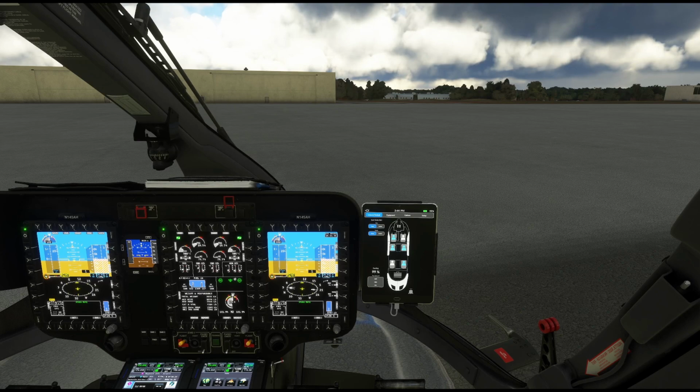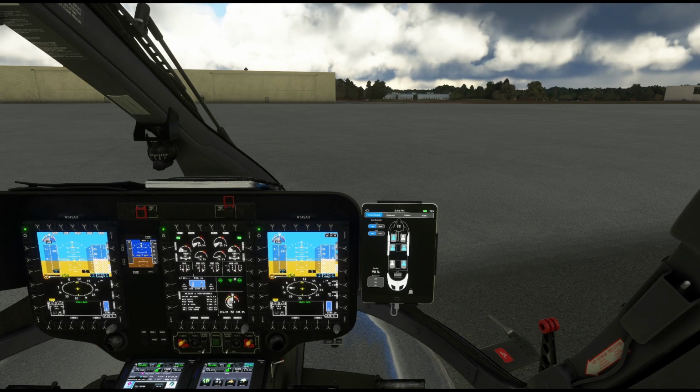All right, so we'll notice up here we have some more symbology. This yellow range is our allowable transient range, and then we have an unallowable transient range in between this red bar and this red teardrop. The red teardrop is going to tell us the absolute maximum. If we exceed that, we have officially exceeded something. If we're in this range, then we have a time limit before we officially exceed something. And this right here, we have a time limit, but it's much more permissive.